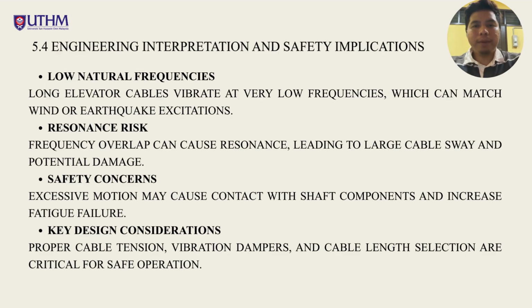Continue with subtopic engineering interpretation and safety implication. From the result, we can see that long elevator hoist cables in high-rise buildings have very low natural frequency. This is important because this frequency often falls within the range of wind or seismic excitation. When the excitation frequency matches the cable's natural frequency, resonance can occur.